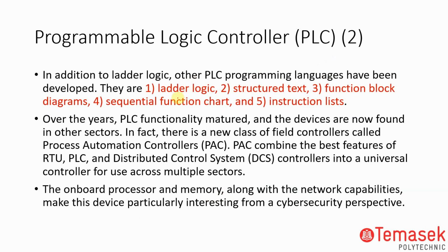The first one is ladder logic, a UI, low-code based. The second one is the more common one, structured text, the standard programming like your C programming, so you have an if-else statement and so on and so forth. And then you have a function block, which is also a low-code system. You have one block by itself to do the coding. It also has a sequential function chart and instruction list and all of this.